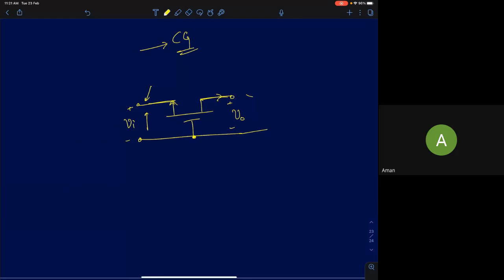Now analyze the circuit intuitively. If I change Vi, the load current here is I0. I0 is the output current. Is there a relationship between I0 and Ii? Is there a relationship between the input current and the output current? Ignore R0 for the time being. Is there any relationship between input and output? Yes, right, they both are exactly the same.